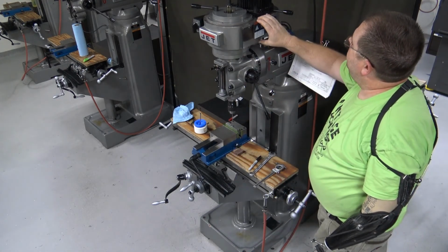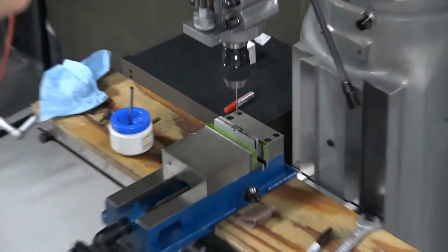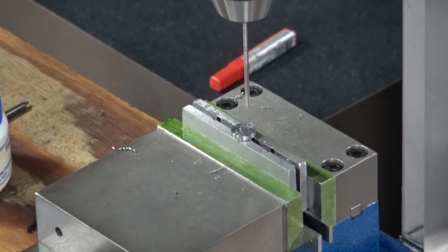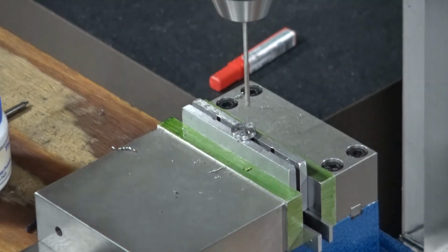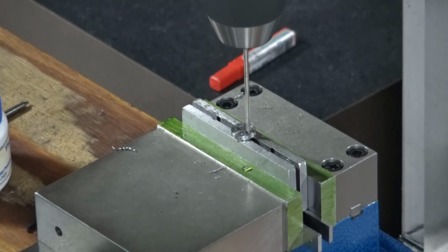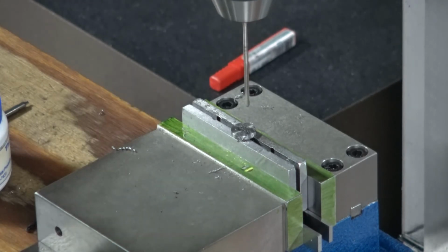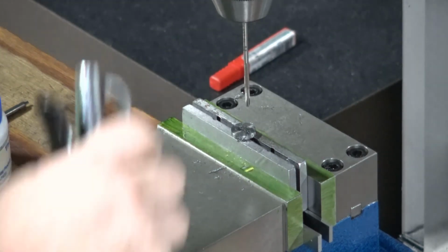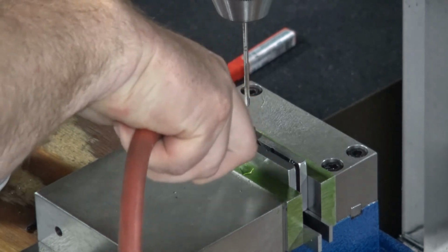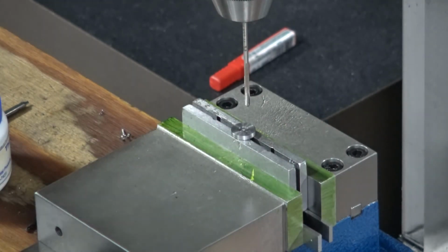Make sure you put that cover back on before you start the machine back up. And now in forward high. Now in forward high, we're running at 1,000 RPM. A little bit of cutting oil. I'm going to feed nice and steady down through. Once it breaks through down at the bottom of the hole, I'm going to pull it back up out. Okay? There's very little cutting force that you're going to run into with that operation. So now we've got our hole.